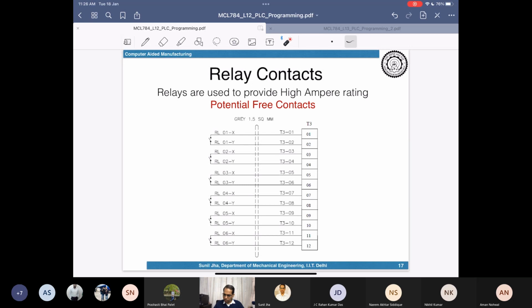So if I want to operate a fan, for example, let me just draw that. So if I am supposed to operate a fan, this is your AC signal, 230 volt AC. And what I will do, I will just connect the fan like this. So what you have done here, one wire of the 230 volt AC I have directly connected to the fan. Another terminal is coming through this relay. So this wire is now going into this relay, and the other contact is basically coming to this fan.